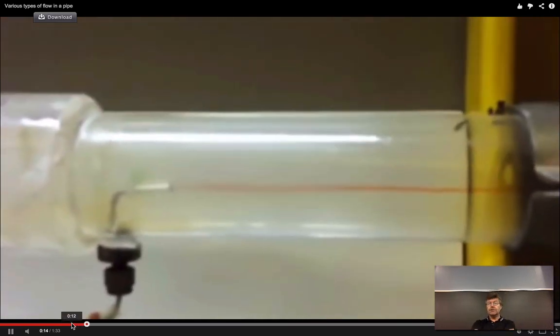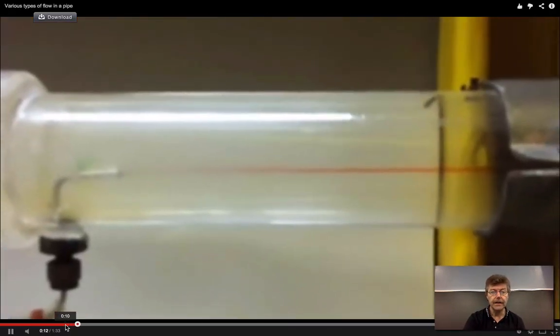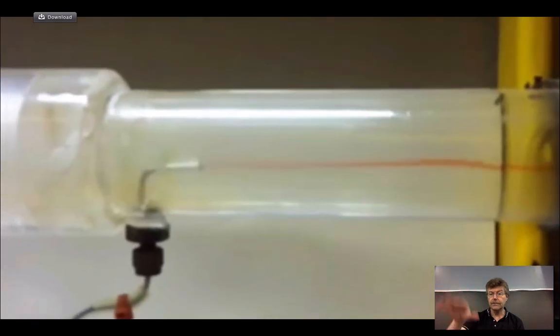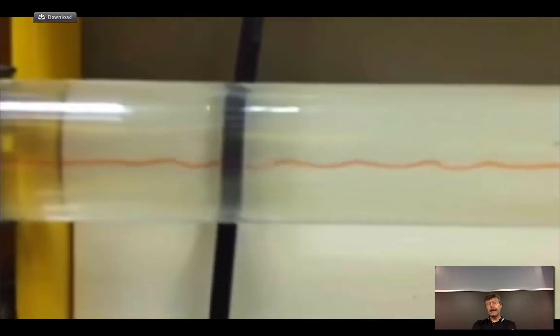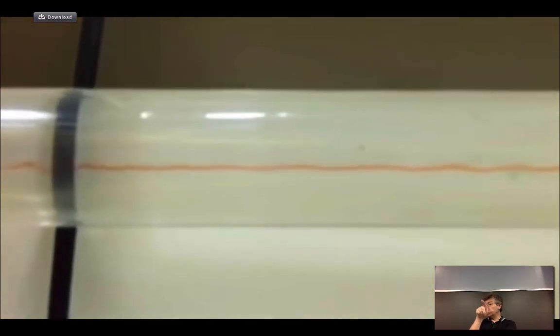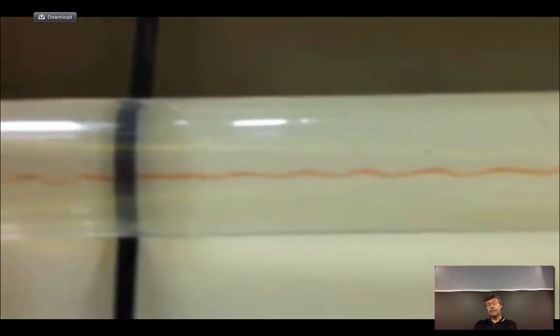Kinematic similitude is important because we want things to be flowing at the correct flow regime. And as we cycle through this, all that's happening in this particular example is that the flow starts off slow and then it speeds up. And you can see as it starts off slow, you see this little wavering in the dye as all of a sudden it starts flip-flopping. And as the speed picks up, because the flow rate in the pipe is increased, then you get a larger amplitude in this undulation, which is really indicative of eddies forming close to the walls. So we want to be able to run our experiments to the right Reynolds number.